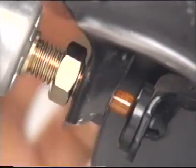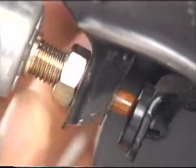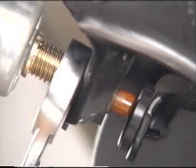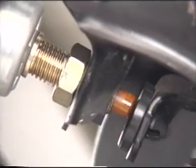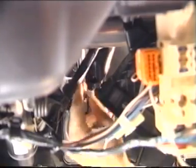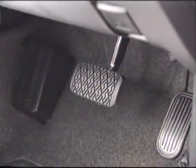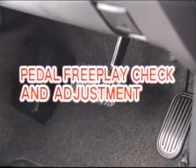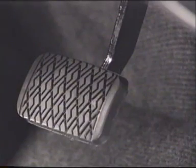Then tighten the lock nut. Connect the wire connector to the stoplight switch. Next, check the pedal free play amount.